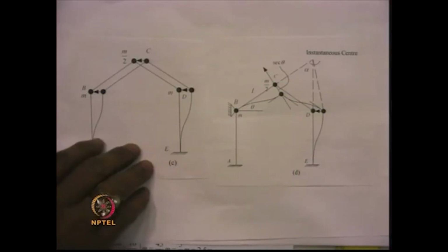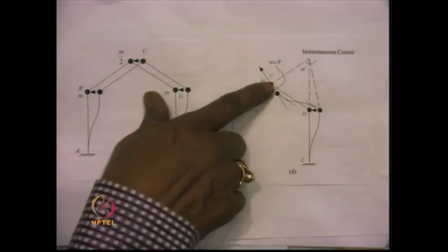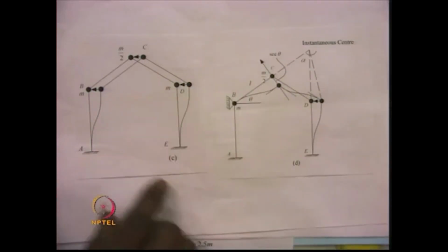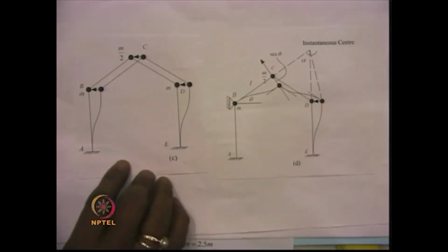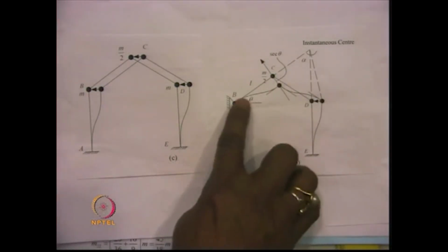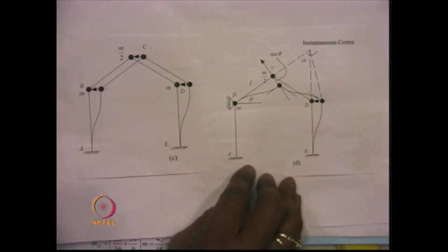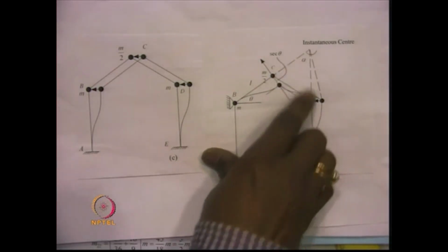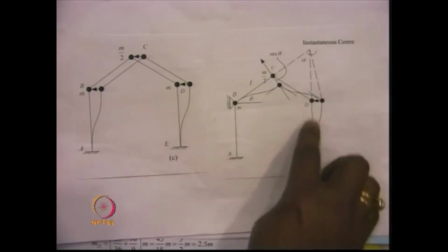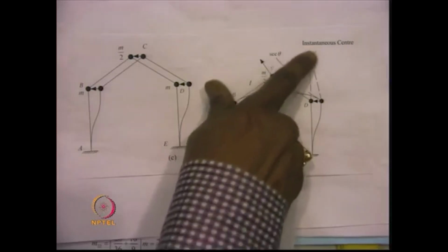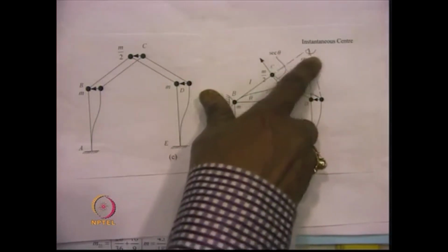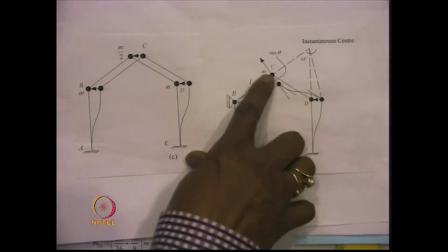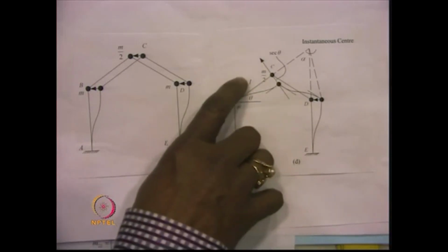Now, if you want to find out m22, then what we do is give a unit vertical displacement to this particular point, to the crown, and lock this. As a result of this, this kind of deformation takes place, and the deformation takes place in such a fashion that the lengths of the members do not undergo any change, and that can be conceived with the help of an instantaneous center of rotation. If we extend this line and extend this line, then they join over here, and this point is the instantaneous center of rotation. This triangle acts as a set square, and if we give a rotation at this particular point, then this point will move perpendicular to the member for small displacement theory.